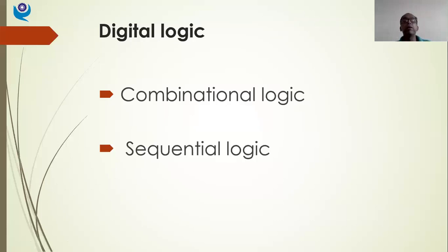And in sequential logic, basically, if you consider some mechanical application of a sequential logic, let us say I have a power press, which is electropneumatically actuated. So I can put conditions where, unless and until the job is fixed in the fixture, the working button of the press should not operate. So these conditions I put.